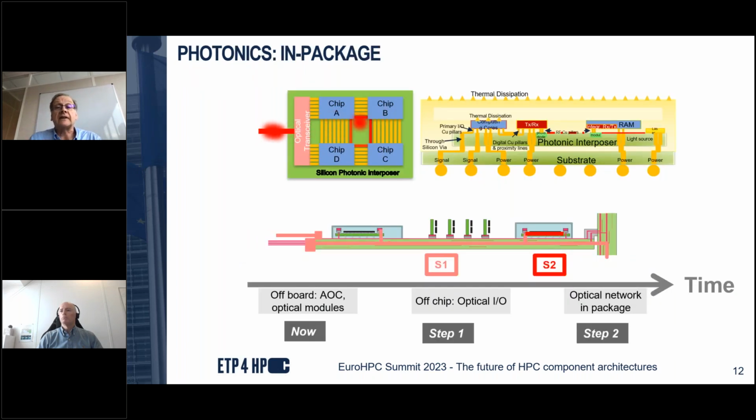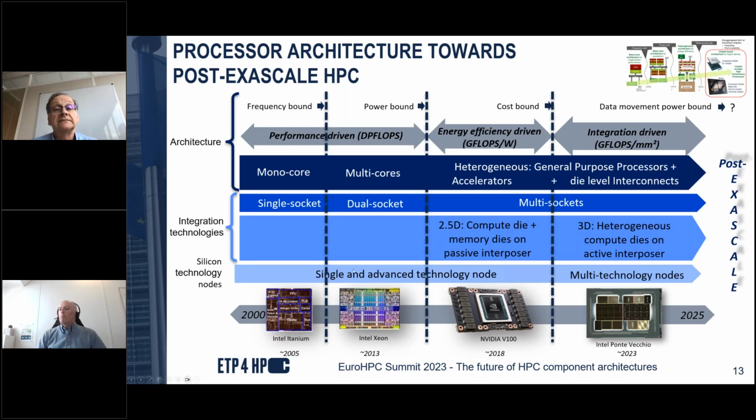So perhaps Craig, you could illustrate this, yes, in the next slide here. So this is wrapping up a lot of the things that we talked about. The slide that Marc showed earlier, talking about the evolution of processor architectures from single core to multi-core. We're seeing that here in terms of products themselves. So you used to see different functional elements in a single chip, as we see here with the Intel Itanium around 2005, and then we started to see integration of vector processing units inside the silicon. And now we're seeing this moving even further with more advanced acceleration and even dual chiplet configurations, to what we see in the Intel Ponte Vecchio with many, many chiplets in an architecture. And as we go forward, we expect this moving to marketplaces of chiplets with standardized solutions that people can drop their chiplets into, and many companies working together.